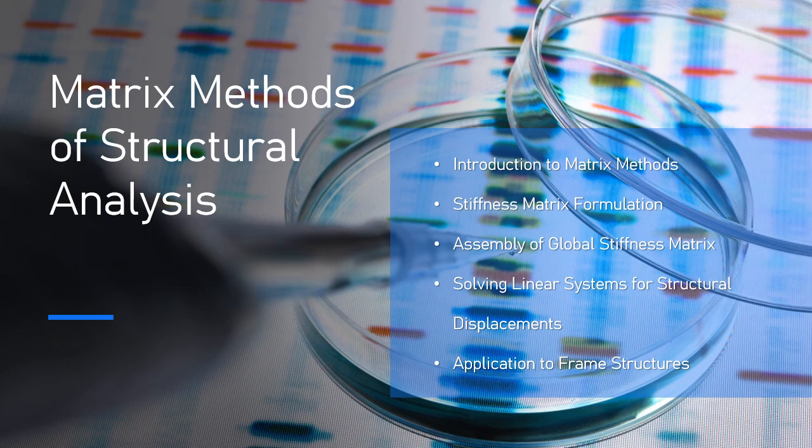3.1. Key concepts in stiffness matrix formulation. 1. Displacement and force relationship. For a structure under load, the fundamental relationship between displacements and forces can be expressed as K·u = F, where K is the stiffness matrix of the structure, or an element, u is the vector of displacements, translations and/or rotations, and F is the vector of applied forces or loads.